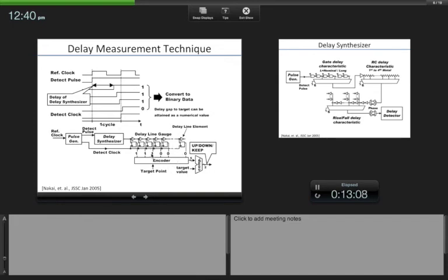What do you encode? You encode where is the transition from 1 to 0. So here the encoder will give an answer 3, right, or 2, depending on whether you start counting from 0 or start counting from 1. Essentially, you are getting a number which is capturing where this transition is happening. That number you take. Now, what you have to do is adjust the supply voltage of this delay synthesizer, such that the edge has traveled a certain distance, right? Say you say my target is I want it to travel exactly 3 units, this plus another 3 units out here. Say that is your target.